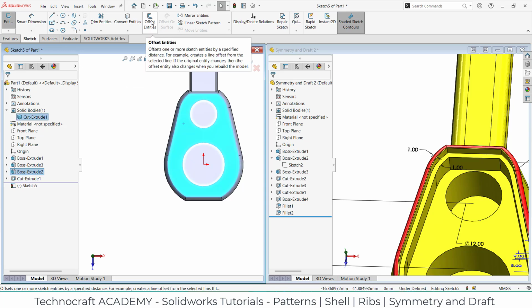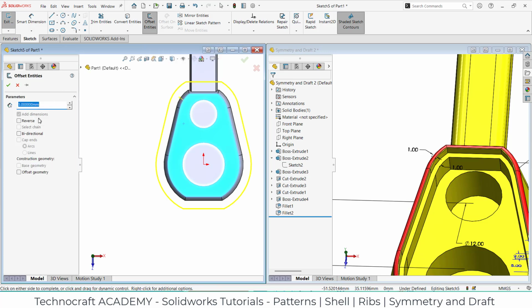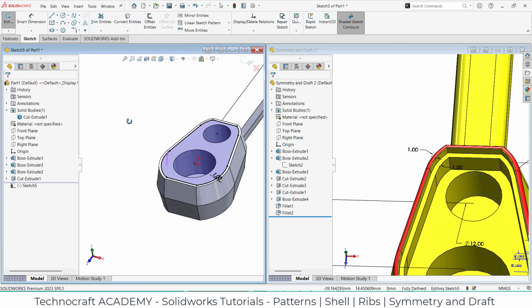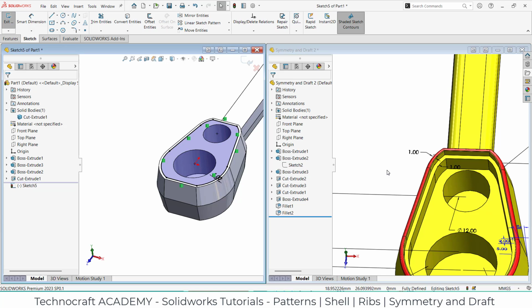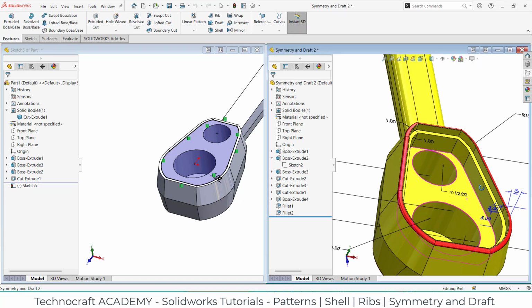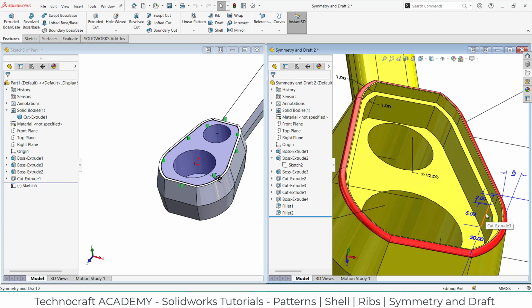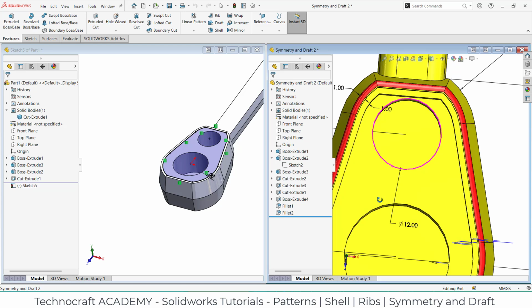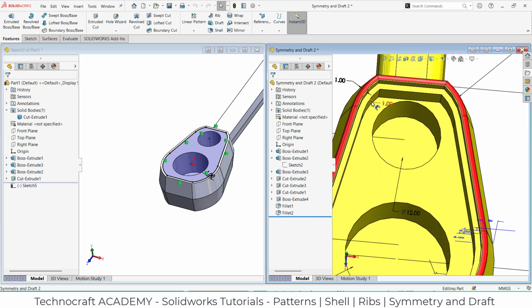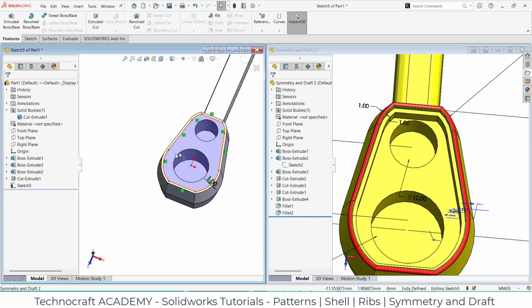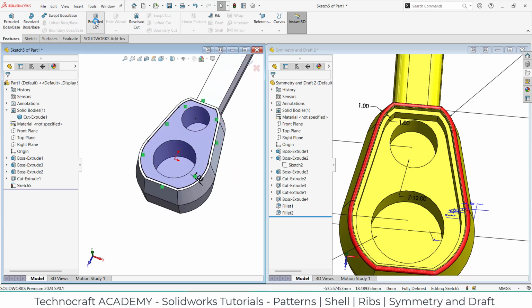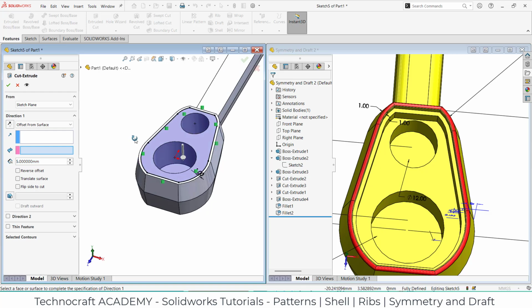I'll select the offset face option, and it should be a distance of 1, and you can simply reverse it inside, green check. And up to what distance should I remove the material? It should be a complete cavity up to this face. It is 5 mm total he has taken. So let's do that. I think there are two steps. One is 1 mm here, again 1 mm inside. So let's try that. First thing, I need to remove the material. Extruded cut up to 5 mm, bottom.